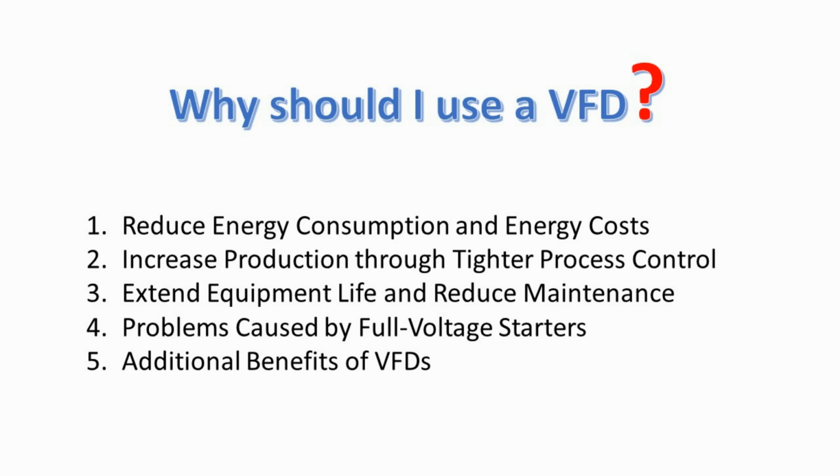When you start a load with a VFD, you will not subject the motor or driven load to the instant shock of across-the-line starting, but can start smoothly, thereby eliminating belt, gear and bearing wear. It also is an excellent way to reduce and/or eliminate water hammer, since we can have smooth acceleration and deceleration cycles.